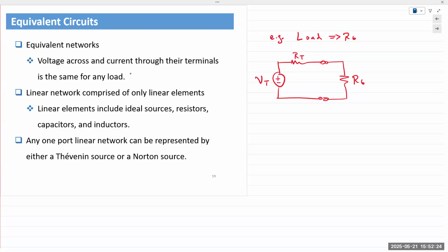All right. So now, if you want to find the value for VR6, what can you use? Your large circuit is reduced to one single voltage source in series with a resistor. What can you use now? Absolutely, voltage division. One-step answer: VR6 is a fraction of your Thevenin voltage. So it's VT times R6 over the sum of the Thevenin resistance RT and R6.